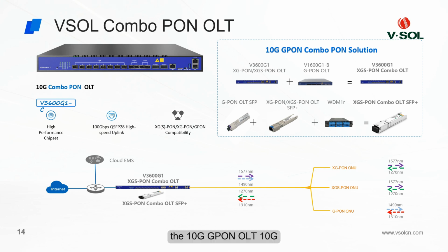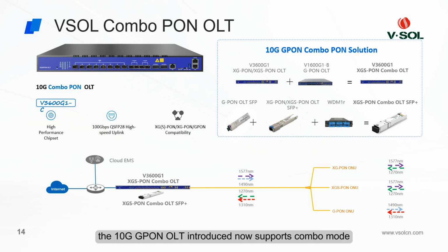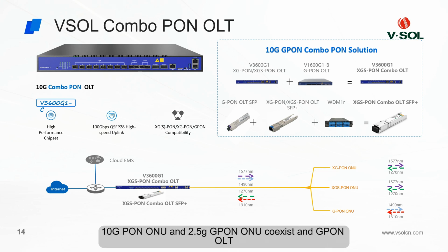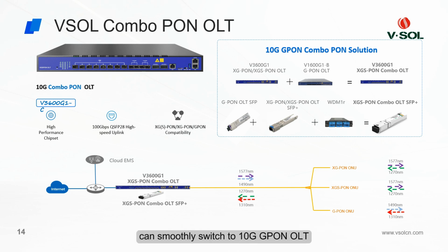The 10G GPON OLT introduced on the previous page cannot connect 10G and 2.5G ONUs simultaneously. The 10G GPON OLT introduced now supports combo mode, which means that in default mode, 10G GPON ONU and 2.5G GPON ONU coexist, and GPON OLT can smoothly switch to 10G GPON OLT.